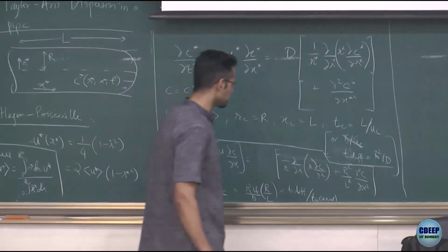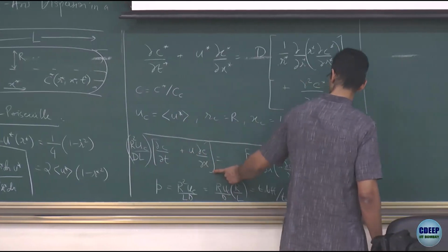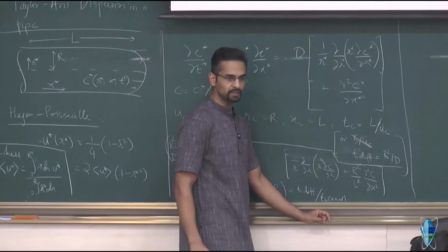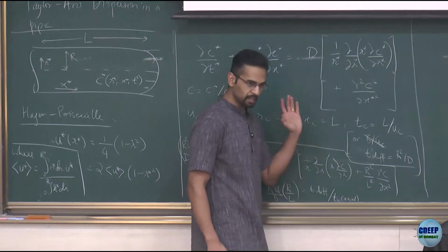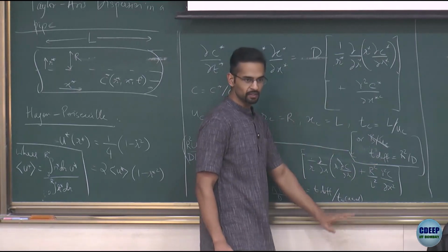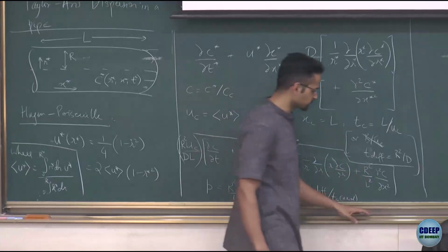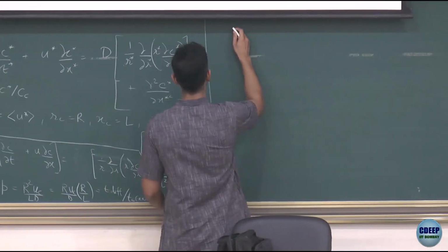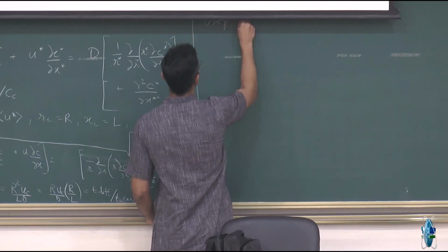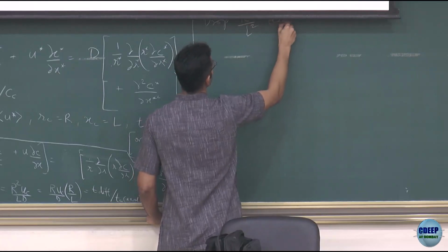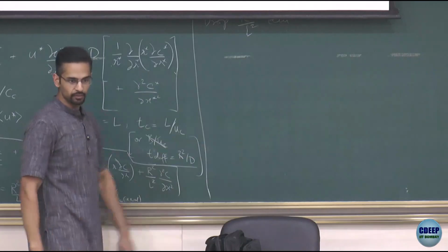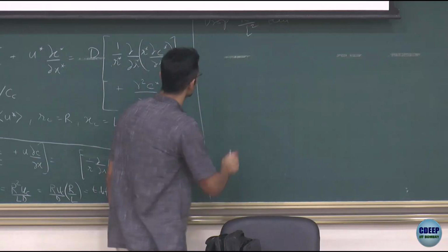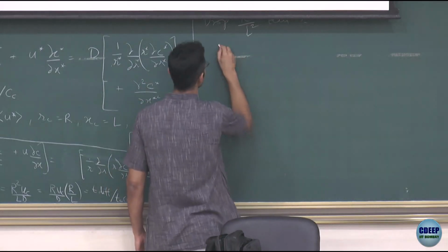So when I do this, you will see that my equation will just have only small p in front of these terms. I'm also, just for simplicity, going to drop this r square by L square, which is obviously small. I don't have to drop it. If I keep it, everything that I'm going to do will also proceed almost without any problem. Right? But just to keep my amount of writing limited, I'll drop it. You can try to include it and see what happens. Okay, but it doesn't change the analysis. So I will drop r square by L square terms, right, which is basically the axial diffusion term, which is small compared to radial diffusion and compared to axial convection. So then after I do that, I will have the following equation.